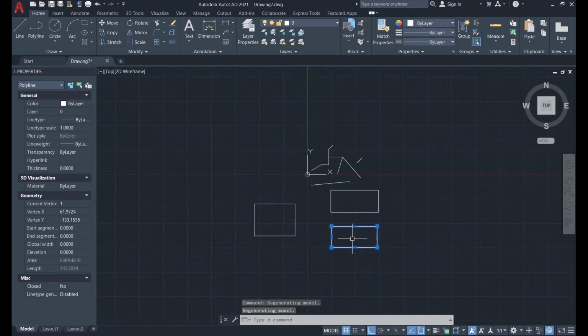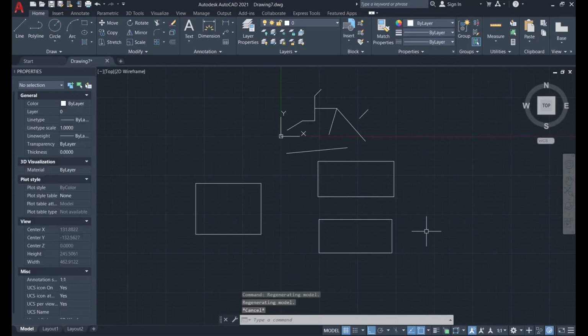That being said, today we have learned about the snap, the ortho mode, the three methods to draw a line, also the object snap tracking to help you to know where some line ends, or when there is a parallel between two lines. You will see this option will be helpful in many other ways. Also, it has a shortcut on your keyboard, the F11. That being said, practice those options.